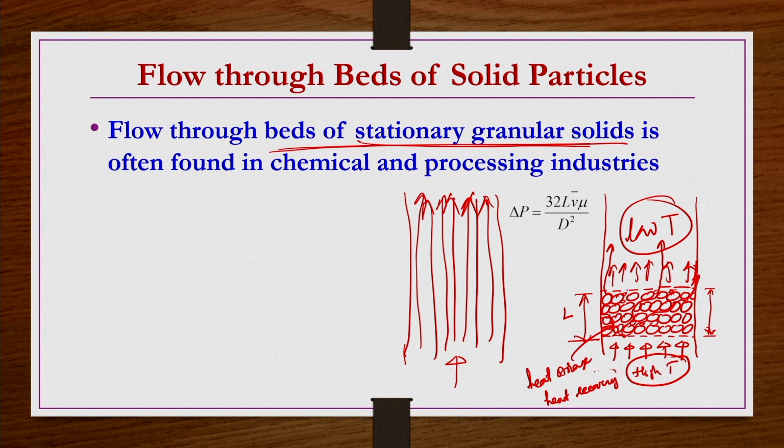Let us say when you want to recover the heat, you can pass a fluid which is at low temperature, and when it passes through, it carries the energy from this heat-stored packing material and goes out at a high temperature. That is also possible. So, both heat storage and heat recovery, these packed and fluidized beds are in general used. Then we have filtration in general.